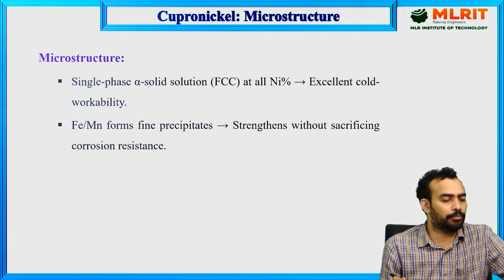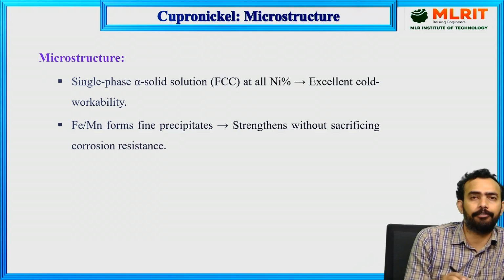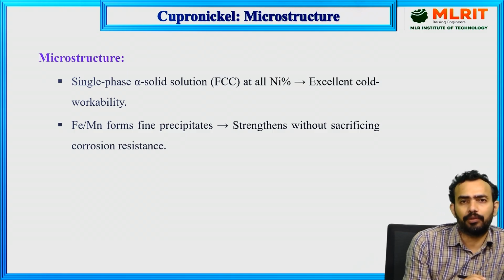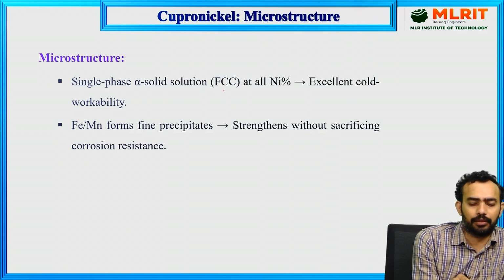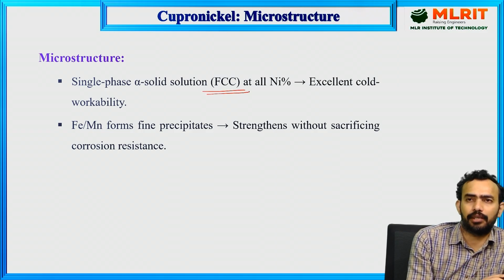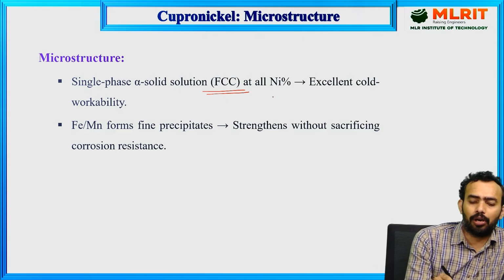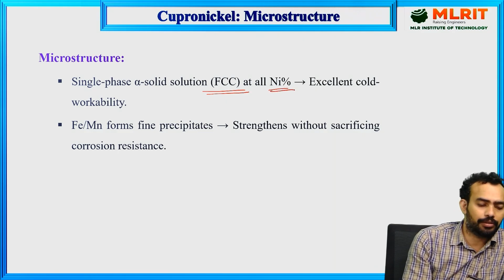If you see the microstructure, we have a single phase alpha solid solution, which has an FCC crystal structure at all nickel percentages, giving it excellent cold workability.